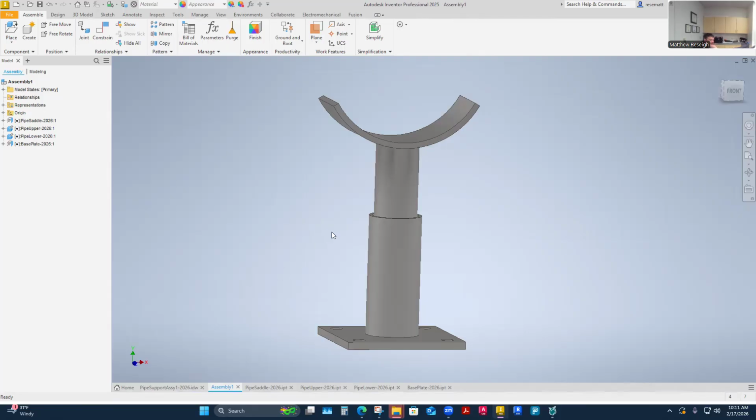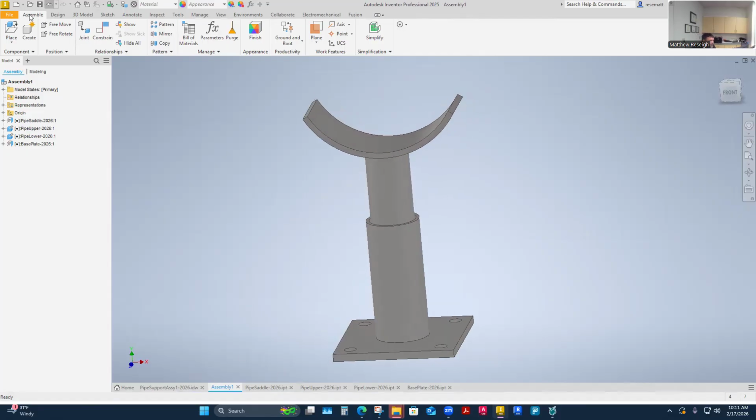My other feeling, the reason why I built it this way, is I'm thinking I should be able to go into my piece of pipe and change it to 12-inch. And everything, the way I've sketched my stuff and projected my geometry, my part should change to accept a 12-inch with just one change on the pipe. I'm going to try that just for my own, a little flex, which you don't have to do. You could save this now.